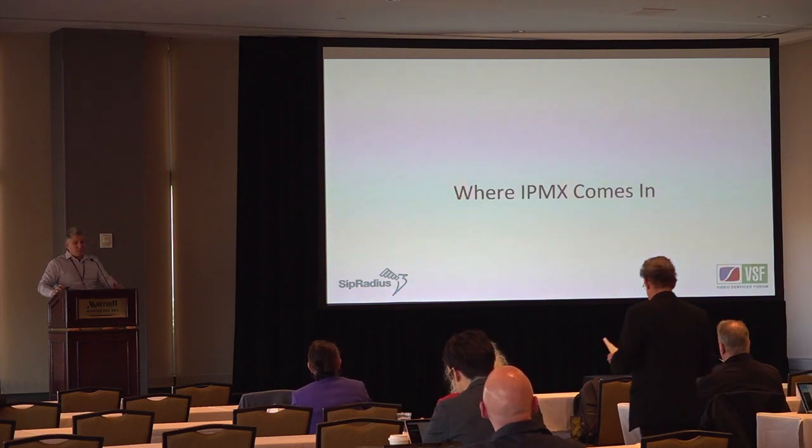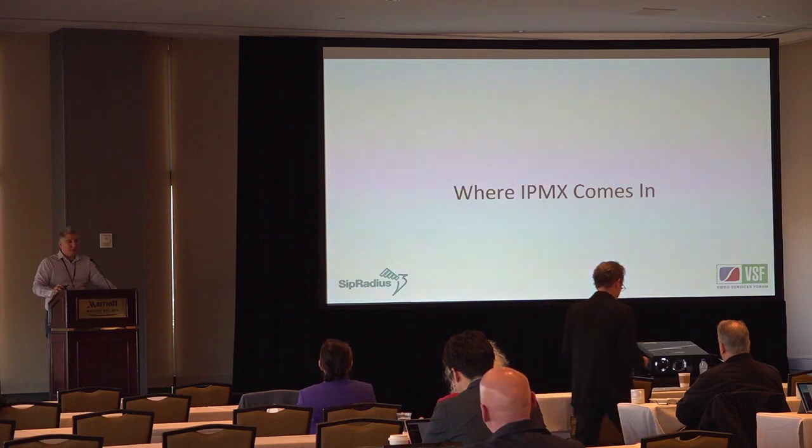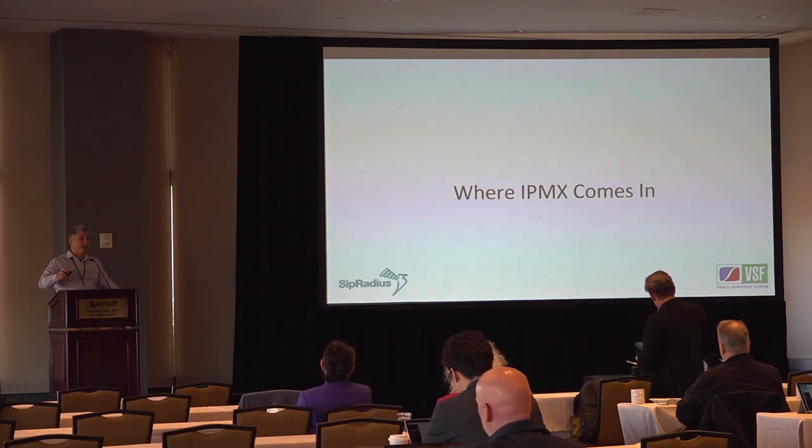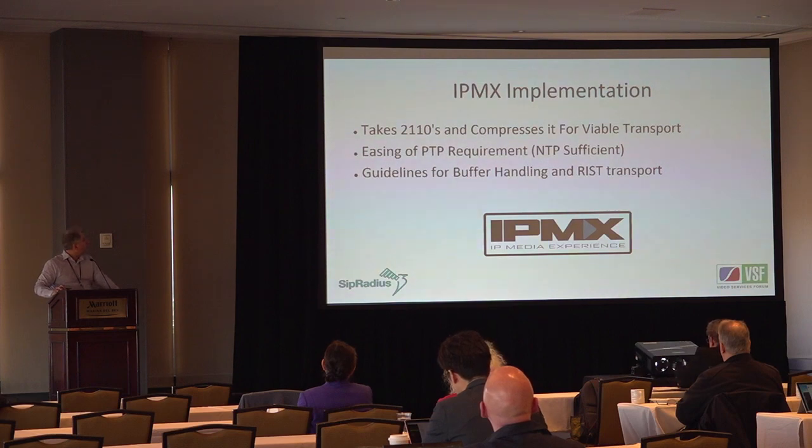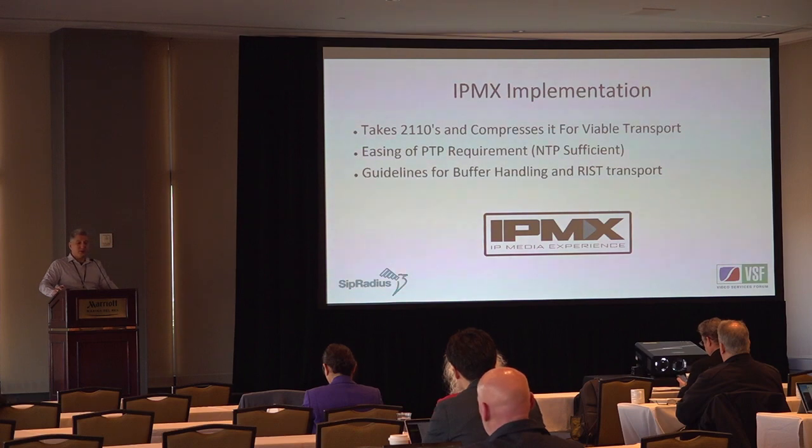So, as we look at the first step, the encoder, we'll start looking at how IPMX fits into all this. So let's talk about the encoders. The encoders are our own high-density 2110 to H.264 hardware devices. They can do 20 encodes on each machine, and every machine includes PTP synchronization software. So we have the clock synchronized to within a few nanoseconds of the local clock source at the different locations.